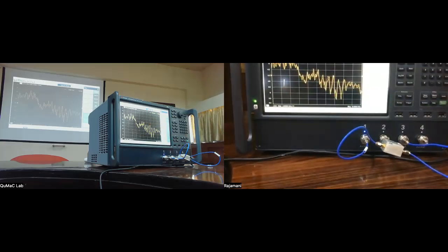The curve looks almost the same, some slight mismatches. This is because this is not exactly the same situation as before, because the 50 ohm termination location is now displaced by a cable. So the cable could have slight reflections and that will affect the overall transmission a little bit. Okay. So the reason I'm over-exaggerating these points is that you should not get bothered by these things. This will take some time getting used to when you're actually using these kinds of measurements in the lab. So you need to develop an intuition for what weird things on the screen one should worry about and what one should not worry about.